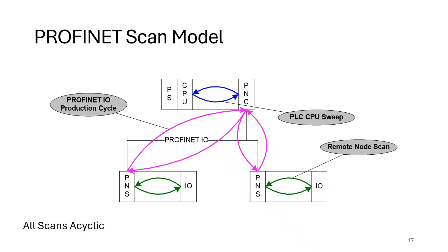So for example, the minimum PROFINET I/O scan is 1 millisecond. So your absolute best response time is going to be 1 millisecond into the input, maybe 1 millisecond in the PLC, 1 millisecond back to the output. So you're probably looking at a fastest response time in the order of 3 milliseconds, but that might be a lot slower depending on how quickly your I/O and everything else operates. But again, for a particular electromechanical device, not a problem. You know, a relay or a contactor could take between 20 and 50 milliseconds to operate. So generally, as long as your control system is faster than the electromechanical part, then there's no problems.